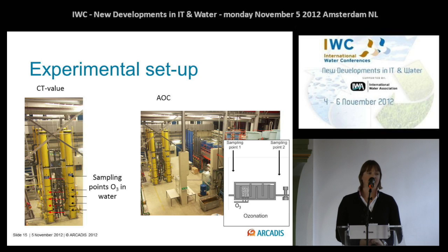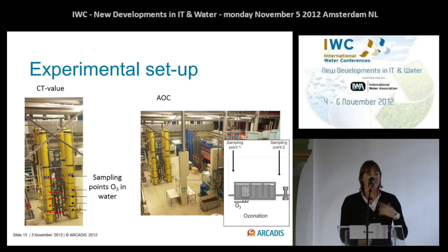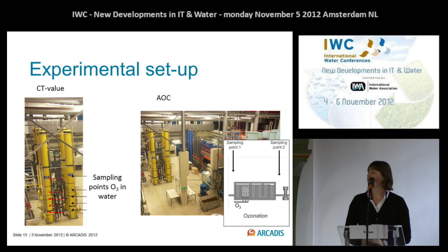And there they have a very nice pilot plant. And in that pilot plant, amongst others, an ozonation system is present, which can treat up to 15 cubic meters per hour. It has the same height as the full-scale plant. With that, we try to be able to convert the results as easily as possible into the full-scale operation.